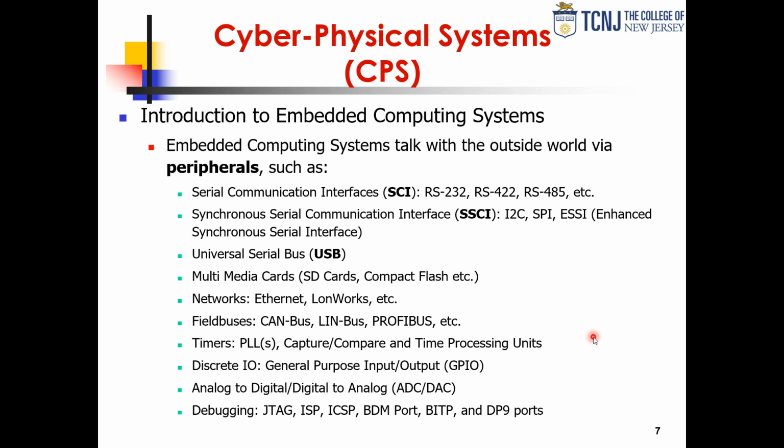And then we have our discrete I/O, or GPIOs. We can turn them on, off. They're actually quite sophisticated these days. Not only do they do 0 and 1, but they also have integrated pull-ups and pull-downs. You can do open drain configurations, which means that you can drive to higher voltages than what the chip can withstand. And you can also, of course, tri-state it. So those are kind of all the functionality of those GPIO pins.